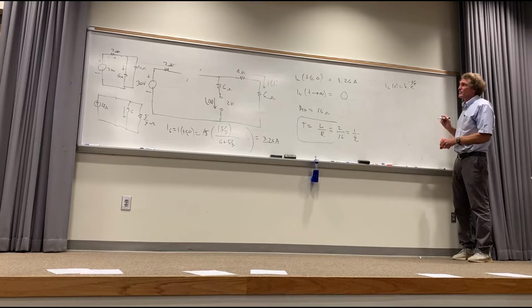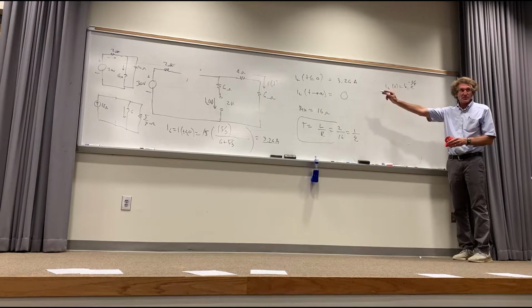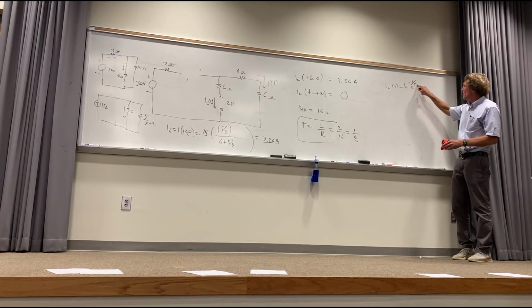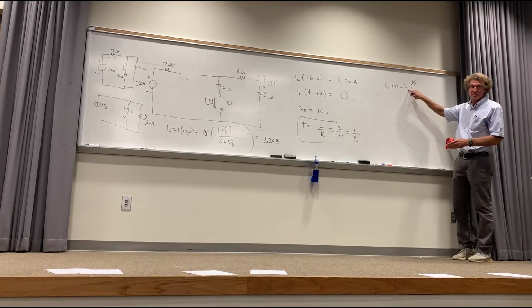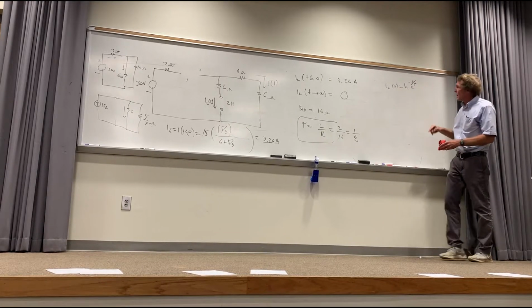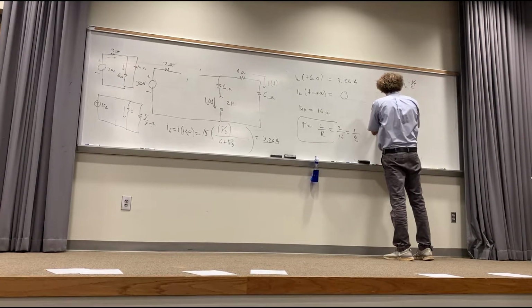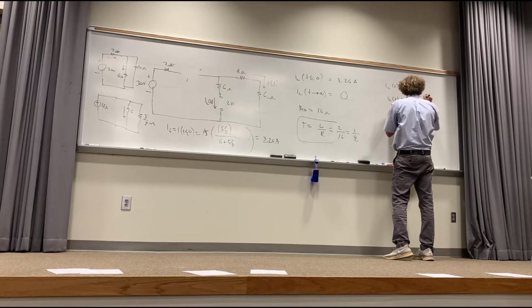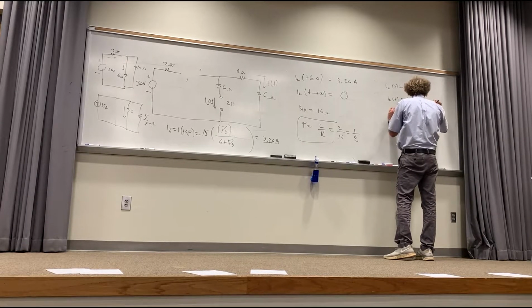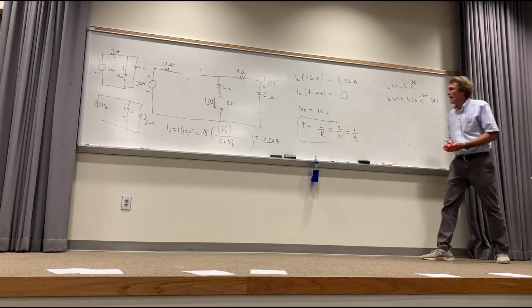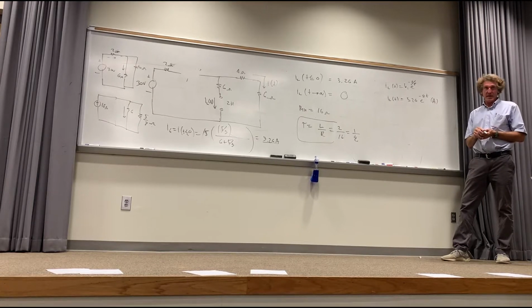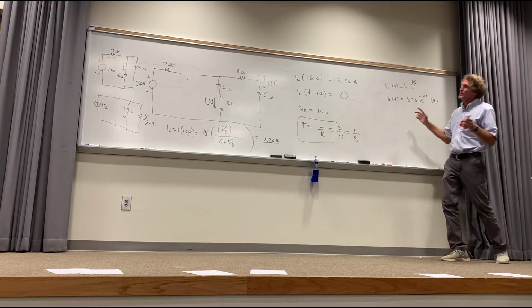Now, what's the current at t equals 0? 3.26, correct, class? Now, what is that? That's this for sure, right? Because t equals 0, e to the 0 is 1. That has to be that, doesn't it, class? So I know for a fact that IL of t now is equal to 3.26 e to the minus 8t amps. And the reason it's minus 8t is because tau is 1/8, and it's e to the minus t over tau. So 1 over 1/8 is 8t. Agreed, class?